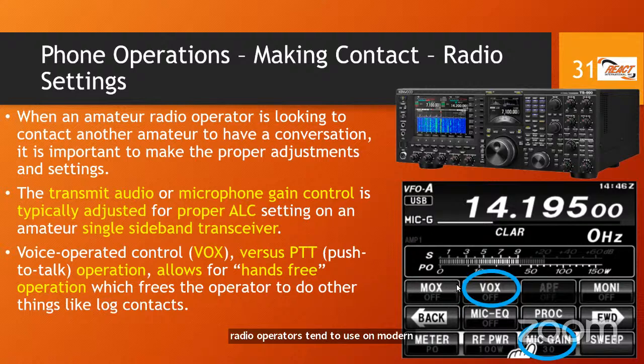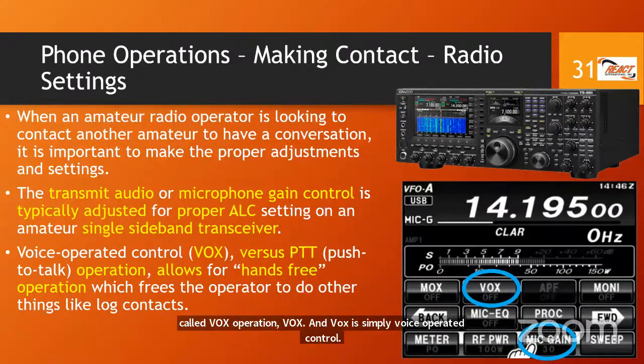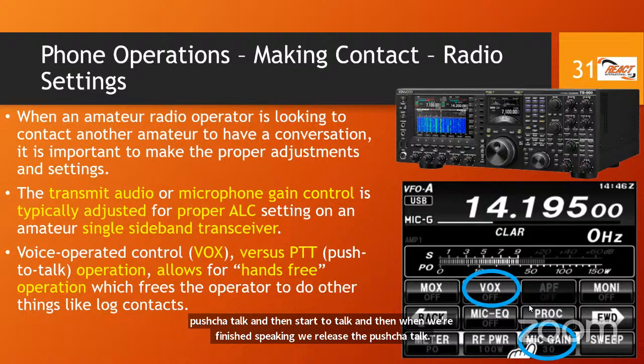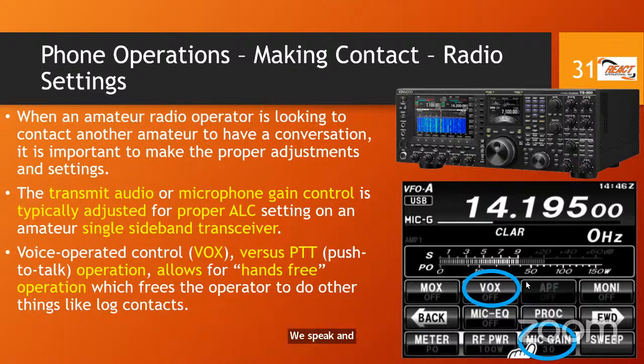It's called VOX operation, VOX. And VOX is simply voice operated control. So instead of using a push to talk or pressing a switch or PTT, instead of pressing the microphone, it's a sort of hands-free operation. Instead of us pressing the push to talk and then talking, and when we finish speaking releasing it, we just speak, and the radio will key up the transmitter on the basis of us just speaking. So that is why we call it hands-free operation or VOX operation, right? Voice operated control, that's what VOX means, as opposed to PTT or push to talk operation.